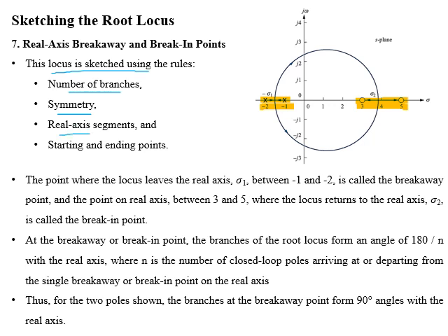The real axis locus will exist between two zeros and between the two poles. The poles of open loop system will act as starting points, whereas the zeros of the open loop system will act as ending points. So root locus will start at -1 or -2 and will end on +3 or +5 in S plane.